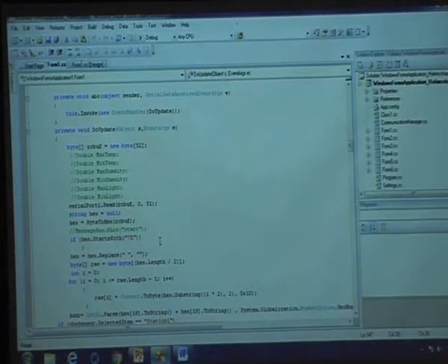It is a very trivial logic, very simple, not an optimized logic, because I have just taken the condition of 7E. But as I mentioned earlier, a 7E can also appear as a data item. One of the frame byte values can also contain a 7E, which must be ignored as an escape sequence. That logic I have not implemented in this simple program, but as a programmer, if you can implement it, that's well and good. I will show you later how that logic looks.